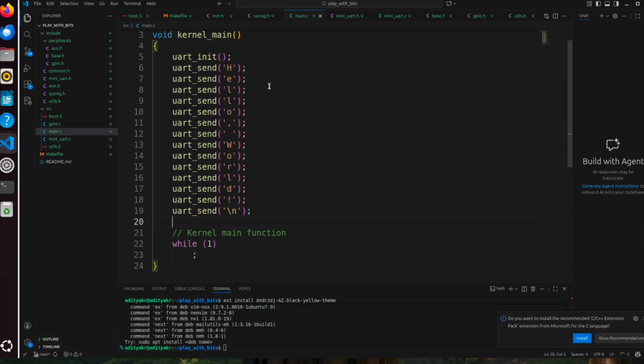It will do this, and then we can also receive. This is for sending, and we can receive that, but whatever is sent from here will go on the UART, and whatever is received right now we cannot print. So what is sent on the UART you will be able to see on the serial console. We are not sending anything from that serial console which will be printed here. So that one we'll try after this.